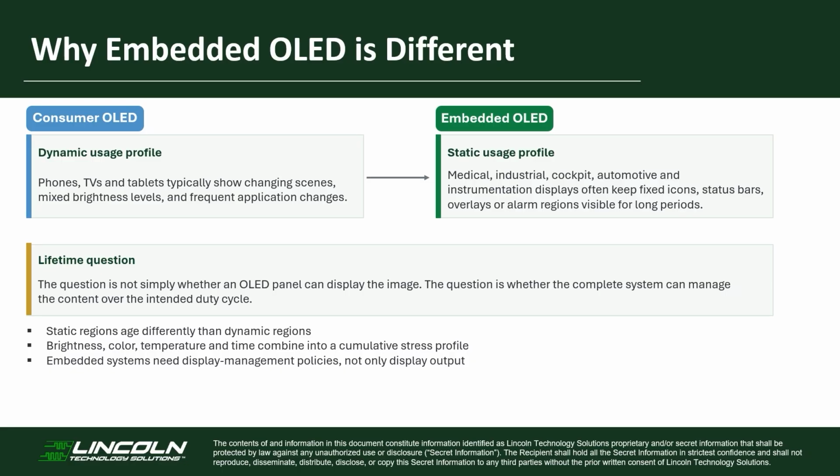That means certain physical pixels experience more stress than others. The lifetime question is therefore not simply whether the OLED can display the required image, it's whether the complete system can manage that image over the intended operating profile. Static regions, brightness, color, temperature, and operating time all combine into a cumulative stress history. Before discussing how to manage that stress, it helps to define what people actually mean when they say burn-in.